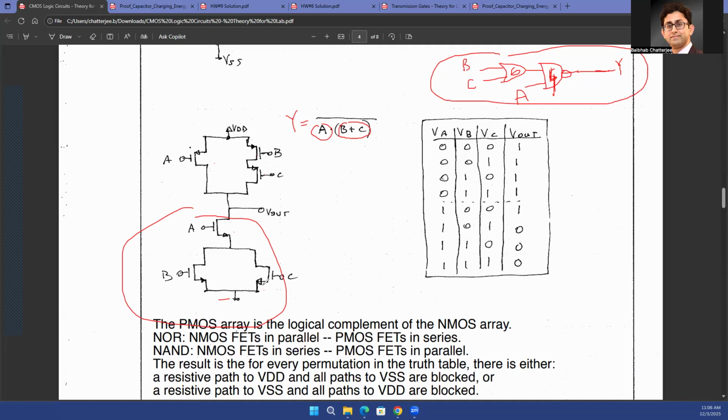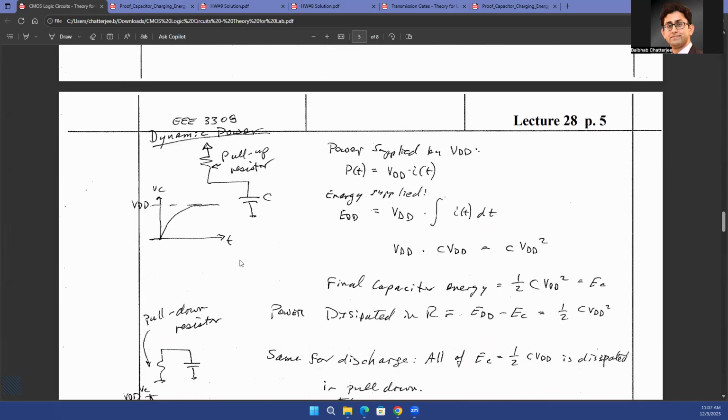And in circuit design, the more transistors you use, that is real estate, basically. The more transistors you use, you're using up area, and area is real estate in circuit design. So if you can use fewer transistors, it's always more useful, because less area, less power consumption, and you can have other functionalities in the area that you have saved. So that is the biggest advantage of implementing the entire logic using CMOS instead of dividing it into smaller gates, or let's say universal gates, and then trying to implement them using universal gates. But very important question. Thanks for bringing that up.